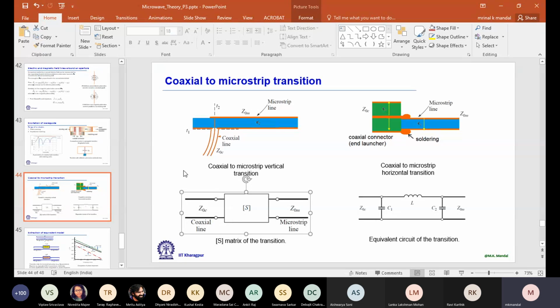And we have a separate calibration method. It is called TRL calibration. Maybe while doing practical classes, we'll discuss in detail. Through, reflect, line. So where actually we can take care of these adapters and we nullify their effect in the calibration process itself. Okay. So here just for some idea, and you should remember this point, that this adapter can change the expected result of your device, because it also has some S parameters.